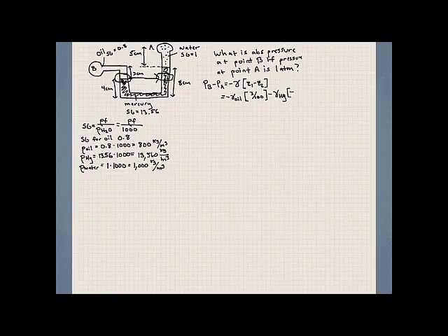And remember, for the same fluid, pressure is the same as we traverse across our system. Okay? So we're really interested only in the column height that has been above this location. And that height is only 4 centimeters.